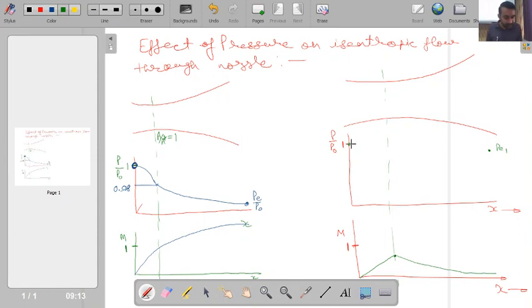Fine. Then corresponding pressure profile, if you see, initially we are having converging section. So in case of converging section, as velocity will increase, pressure will keep on decreasing, reach a minima at the throat, and after this point, because the flow velocity is decreasing, we will be having regain in the pressure, and then it will once again try to reach at this point. Okay, and if I now slightly decrease the pressure ratio, say if in place of PE1 I take some pressure PE2, then ultimately my pressure profile will go something like this, and then Mach number will also try to lift up.